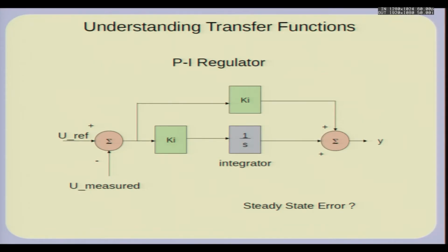In fact, for most regulators, although we do use lead functions, lag functions, the first order filter which we saw, also sT upon 1 plus sT if we want to remove some transient components, the steady state offsets, etc. These are all blocks, kind of transfer functions, in the toolbox of a control system engineer, and he needs to use these appropriately so as to tailor make his dynamical response to what he wants.